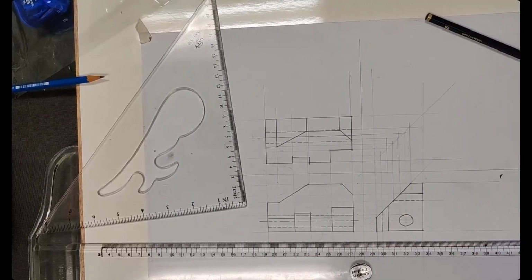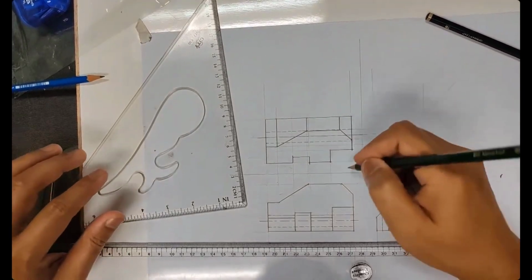But okay, I need to ask you guys. We have a cutout. When we look at this block, we have a cutout of 20 of deep 10, and cutout of 15 of deep 5. We better show that dimension to the correct view that really represents the profile of the cutout. Do you understand me? That cutout 20, 10 and cutout 15, 5, to which view should I put the dimension? Do the small dimension first because your maximum length will be the outer one. Yeah, you are right. Top view clearly shows the dimension of the cutout.